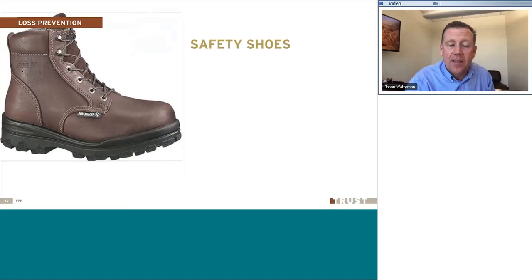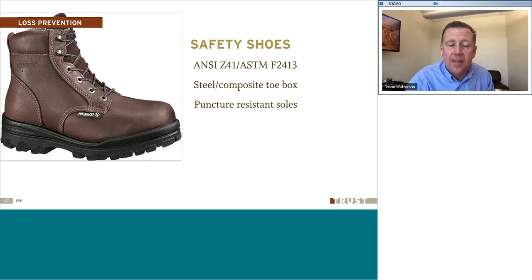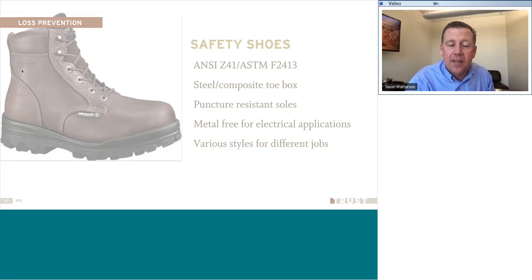So he cuts through this material, and a piece of slag falls off, hits the top of his shoe, and melts immediately through this mesh material and drops onto his toe and causes third-degree burns. And of course, it went into his shoe and he couldn't get it out. So it's burning and burning. Anyway, use the right type of shoe. Just because it meets the ANSI standard doesn't mean it's right for the application that we're using.